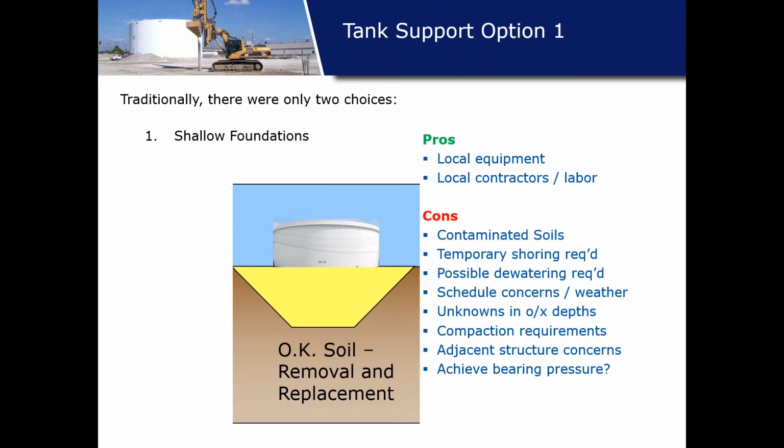It's a massive earthwork. Depending upon the adjacent construction, you might need shoring. As I mentioned previously, if groundwater is shallow, you can't perform the over excavation activity without having dewatering pumps. If it's rainy weather, the material is wet, everything is stopped. You really can't perform this activity. This also applies to the structural fill. If it's wet, you can't get compaction of the wet material. Also, by doing all these studies, all these explorations, and performing the over excavation and structural fill, will it provide the adequate bearing capacity you're looking for? Sometimes not.